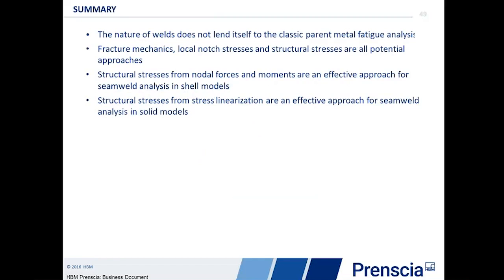Finally, in summary, just what I was trying to describe is the fact that welds do not lend themselves to a classic fatigue analysis process. We don't have detailed geometry. We don't have detailed materials. So what we do is go back in and use structural stress approaches inside of DesignLife to allow us to analyze those. And again, in DesignLife, we're using structural stresses from nodal forces and moments to allow us to do welds in shell meshes, and we're using structural stresses from through thickness integration to allow us to do the calculation in solid models.